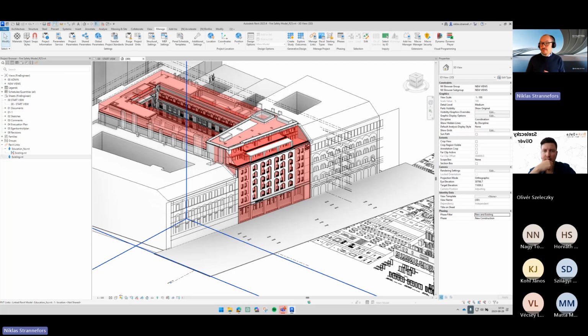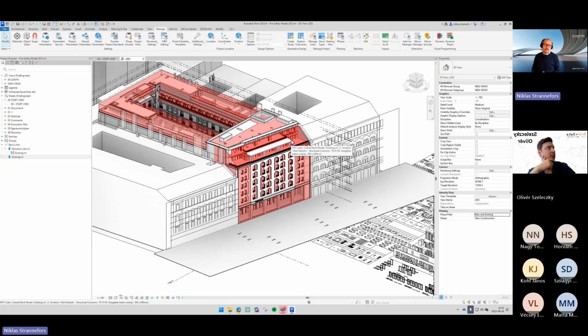Now we want to grab the levels. If we have a new construction, a new building, we don't have to do this with faces because everything is new. It's kind of out of the box. But after this, we want to take the levels from the architect. They, quote unquote, control what we want to see, and we're going to steal their levels. I've already gone through, so I've figured out where things are, but we're going to do the more brutal or blunt way of doing it. We're going to grab everything, and I'm going to explain the steps I usually take when I start this.